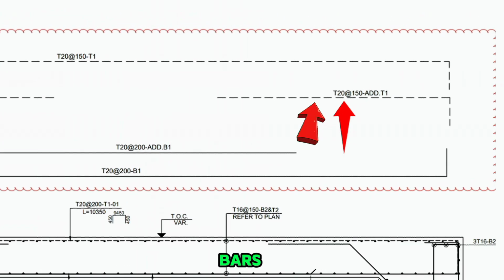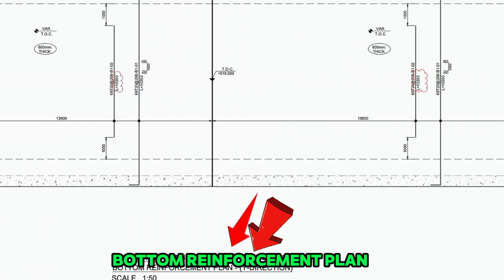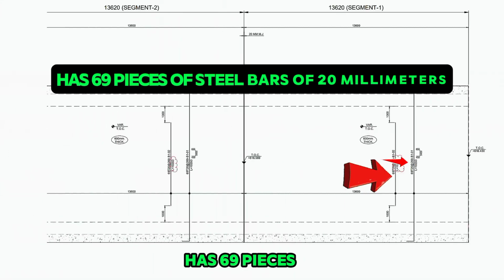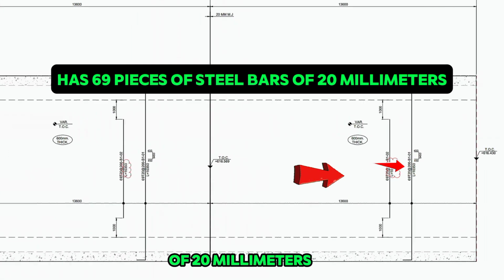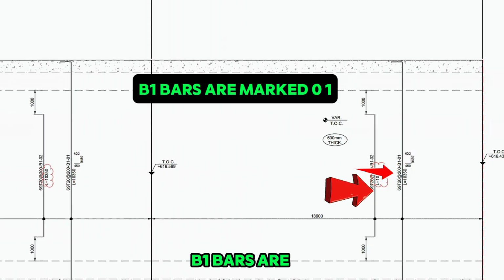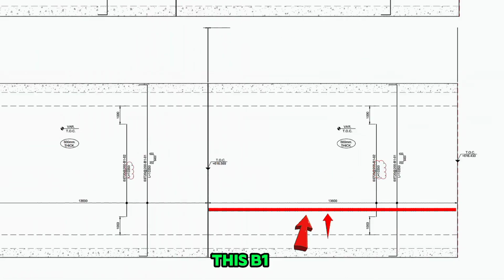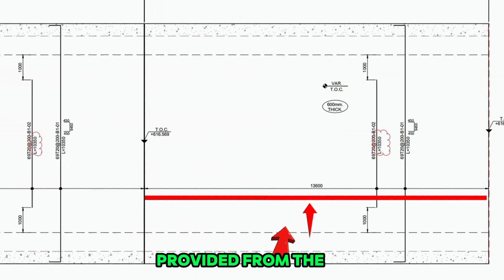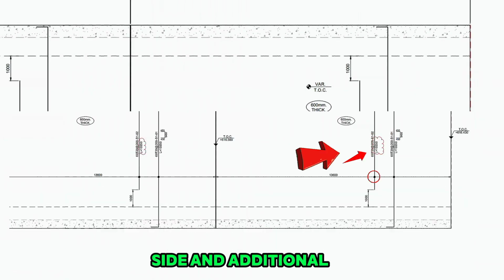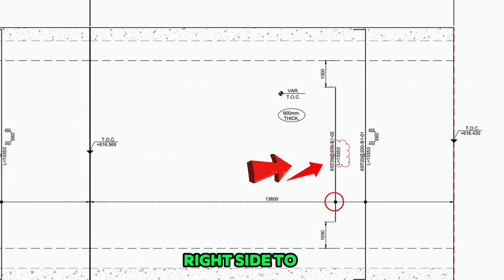The underpass road tunnel top slab segment 1 bottom reinforcement plan in the Y direction has 69 pieces of steel bars of 20 millimeters with a spacing of 200 millimeters. B1 bars are marked 01 and their dimensions are also included. This B1 steel will be provided from the right side to the left side, and additional bars will also be mentioned that will be provided from the right side to the left side.